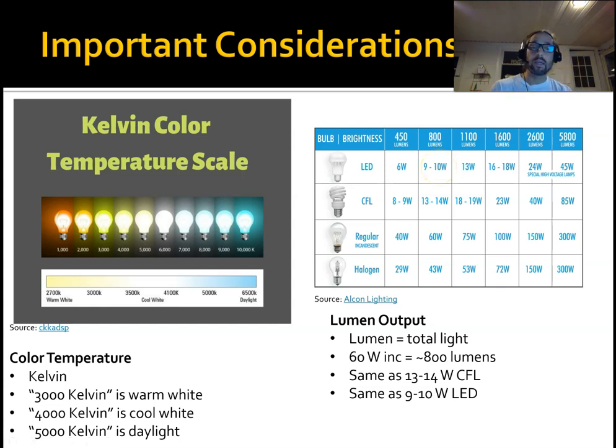So when you replace a light, assuming the light is acceptable in that room, you want to replace it with a lamp that has the same lumen output. Okay. And there are other considerations as well. There's color rendering index and some other things.